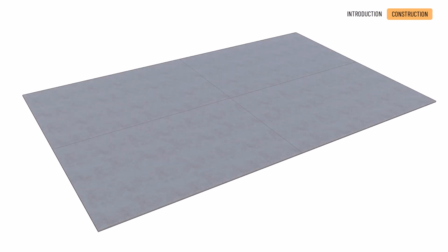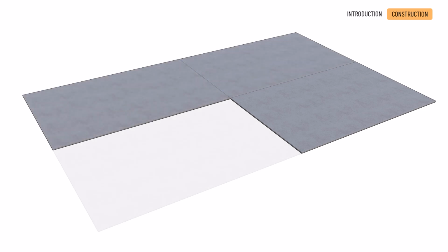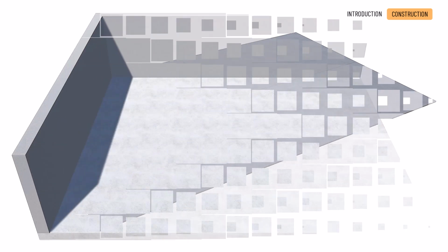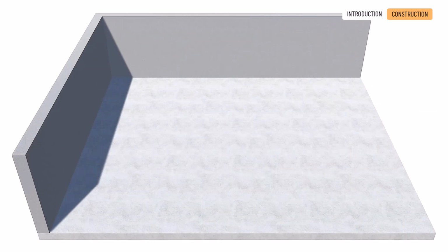Subfloor construction. The subfloor concrete is a 5 to 7 centimeter thick, monolithic, reinforced concrete layer, which must be dilated every 40 square meters to prevent cracking. Here are the steps to construct a floating floor concrete subfloor. Install a 1 centimeter thick edge insulation strip along walls to accommodate thermal expansion and prevent stress-induced deformations.